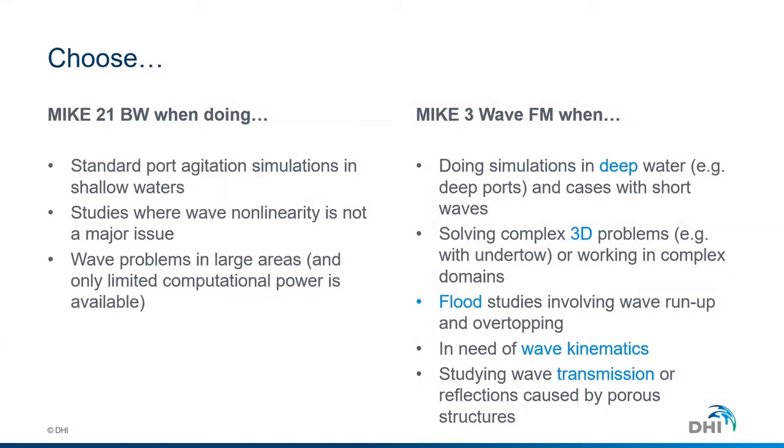Since even though we have this highly parallelized MIKE 3 Wave FM, it is still a high resolution model. It is not a regional model. It is used for more small scale applications. But you can use it also for doing some of these deep water wave transformations, where we have really deep water, so large kh values. You can also consider cases where we have these complex three-dimensional problems with waves interacting and breaking in different directions and spreadings.